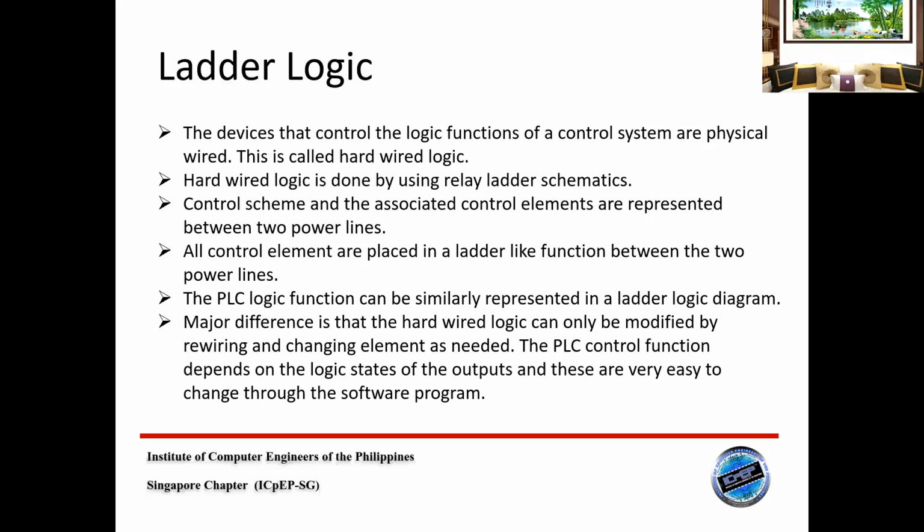So the PLC logic function can be similarly represented in a ladder logic diagram. The major difference is that the hardwire logic can only be modified by rewiring and changing elements as needed. The PLC control function depends on the logic states and the outputs, and these are very easy to change through the software program.